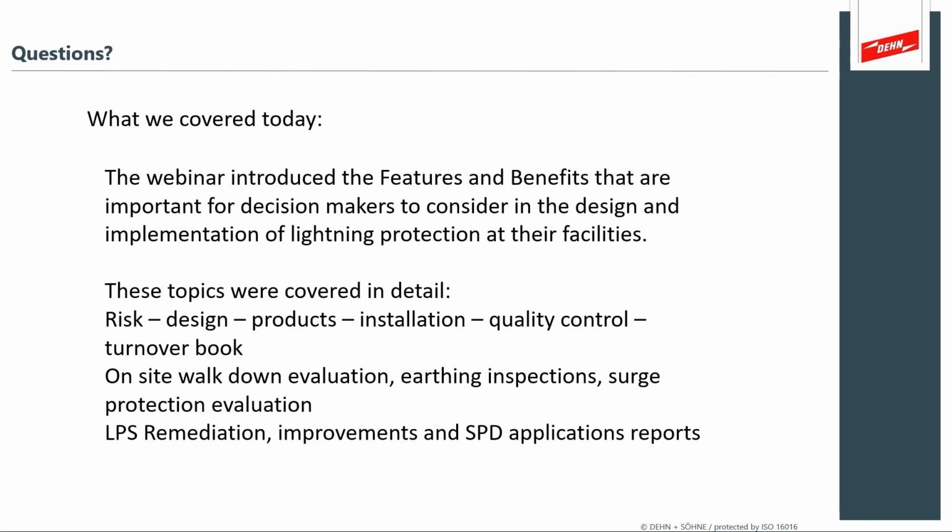The real problem is that you really don't know if a typical AC power SPD is nearing its, quote unquote, end of life. If you're in a high lightning area, it's reasonable to assume that every year you should be inspecting your SPDs. If you have direct strikes on your structure, it's quite reasonable to assume that you need to inspect and evaluate your SPDs.